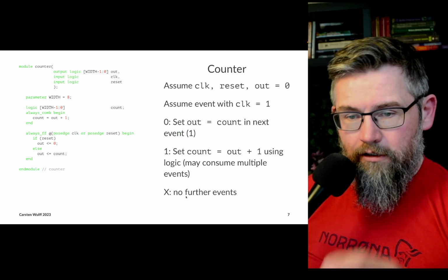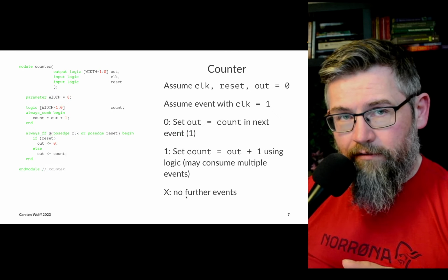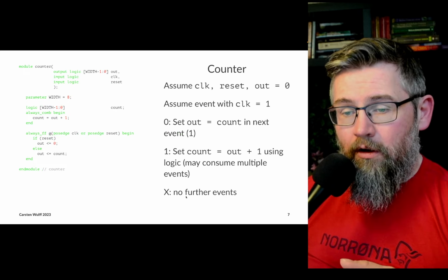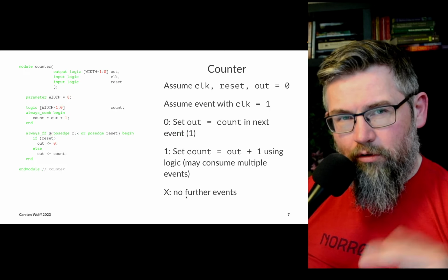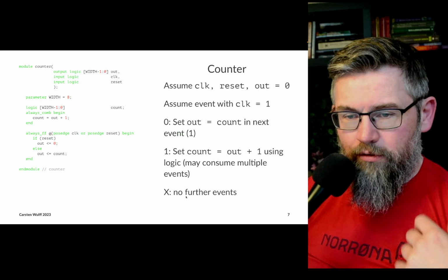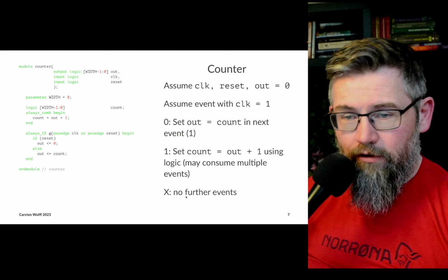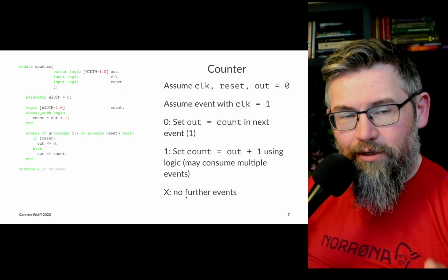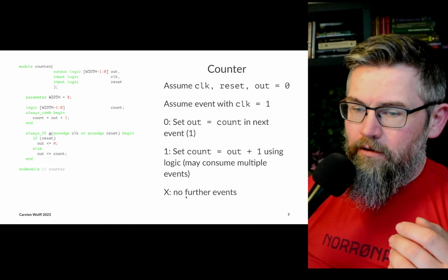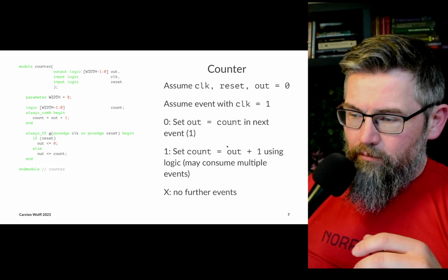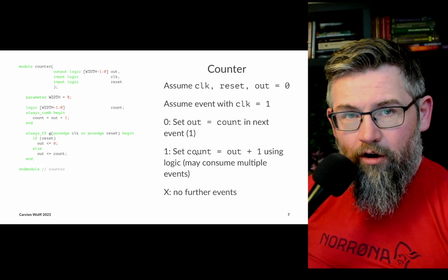So that means in a digital simulator, you have to keep track of the always_ff type of things, what they depend on, and you have to keep track of all the gates and what signals they depend on, but you don't need to search through all of them. Because as soon as you're supposed to do something in the future, you add it to the event queue, and when you're computing what happened at that time step, then it does something. Now, of course, as I said, from the out variable being set until the count actually changes, it will take some time, or a number of events.